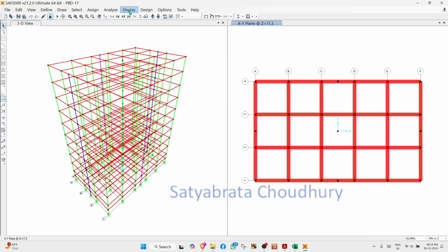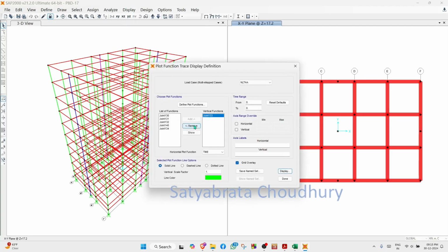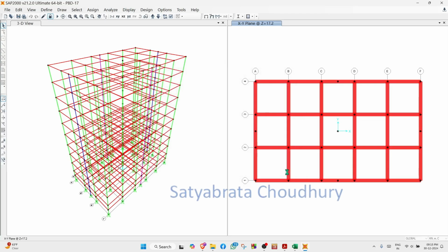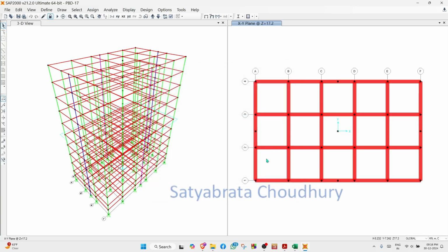So if you want to see the displacement function at the joint at the roof level, then you take this, add to this command and show the display. Then it will show you the displacement history of that floor at the central node. How to capture the data behind? You can go to the file and give print tables, and you can print to an Excel file. So that way we have printed it to an Excel file, and we can show the files here.